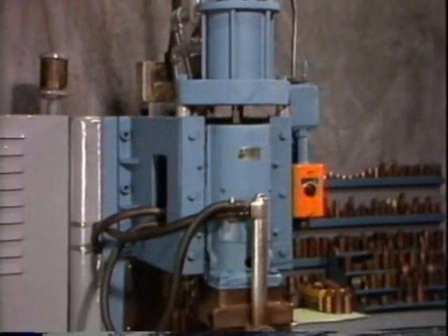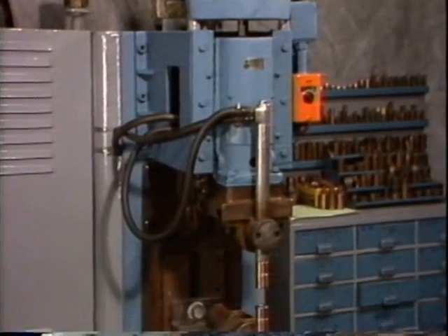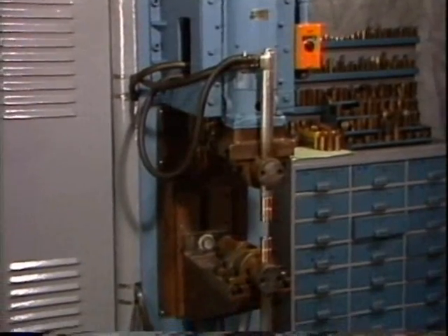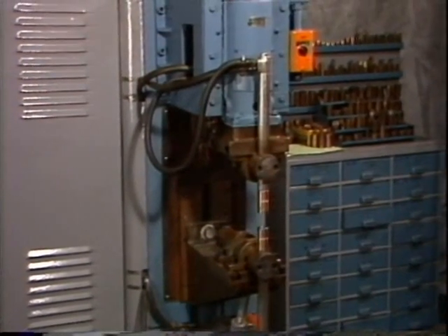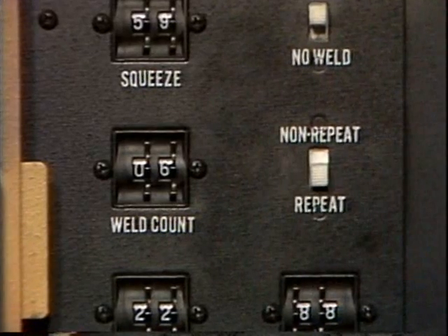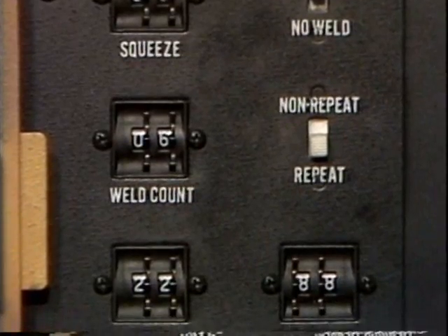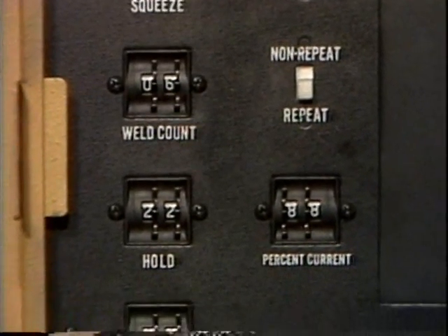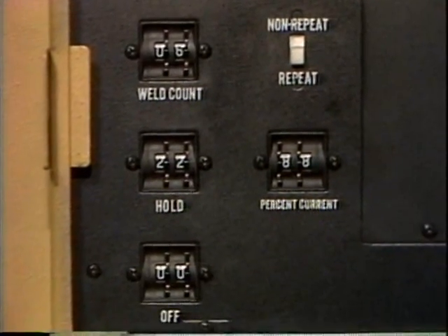It is recommended that all projection welding be done on a press-type welder. This type of welder has an air cylinder or hydraulic cylinder directly over the electrodes. Its travel is in a straight line. It is important to have good alignment and equalized pressure at the electrodes. Electronic controls to maintain the proper relationship of heat, time, and pressure are important to achieving optimum welds.